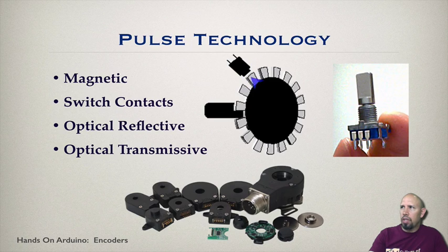Whenever one of these fingers gets close to the electromagnet, there's a change in the voltage associated with that electromagnet, and so you can detect those changes. The closeness to iron or a magnet will give a particular change in this magnetic pickup.